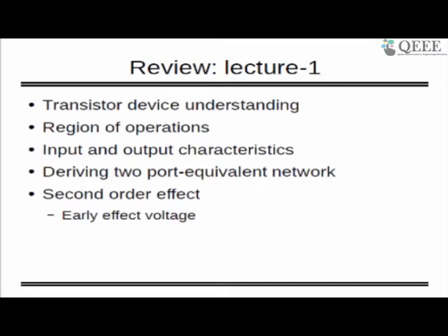But there was one question in the first lecture itself: why only the Y parameter? We follow it because it looks easier to find the input and output impedance. Input and output impedance are very important, because there should not be any loading if you are connecting two circuits. So one should know what quantity they are going to connect to another one.